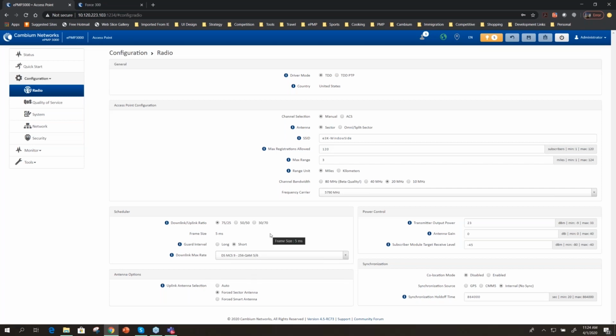That beam steering antenna, if you have it on your network, go ahead and use it with the 3000. But the 3000 has a considerably narrower sector antenna at 65 degrees. It also has a 4x4 receive. So combination of those things, we don't believe the beam steer antenna in the 3000 will make as dramatic of an impact to you as it did on the 2000. It will help you in certain cases. So if you have the antenna, attach it, use it.